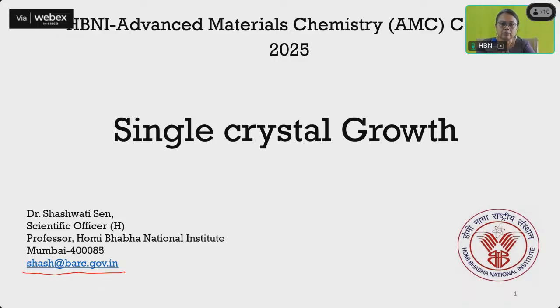We also learned about compound semiconductors, especially gallium arsenide, and why they are important: the band gap can be tailored, and generally compound semiconductors are direct band gap semiconductors, so they can be used in optical applications like light emitting diodes, LEDs.